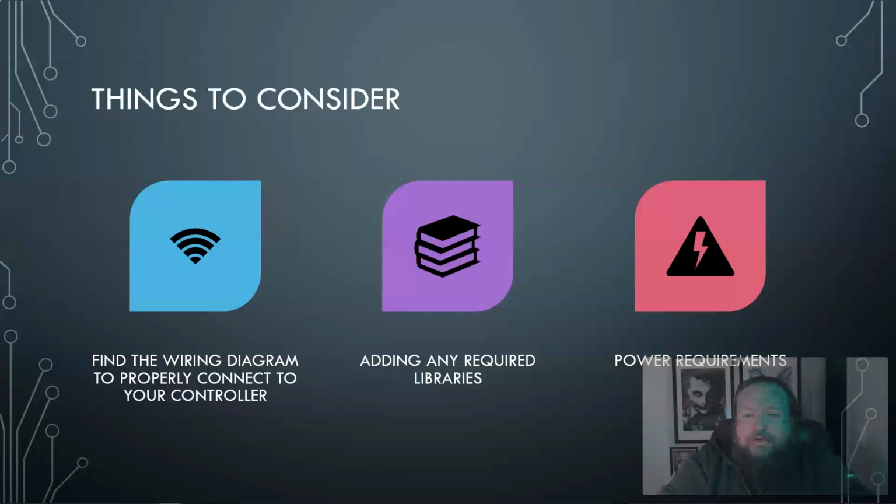Are there any additional libraries that have to be installed into your development environment that help with the communication and working with those sensors? Like Arduino itself has a lot of libraries that come standard, but a lot of times when you're working with other companies, say like Adafruit, in the standard install, you're not getting those libraries, so you need to go through and either manually install it or use the actual library manager feature that's built into the Arduino IDE to download those new libraries to get that to work properly on your device.